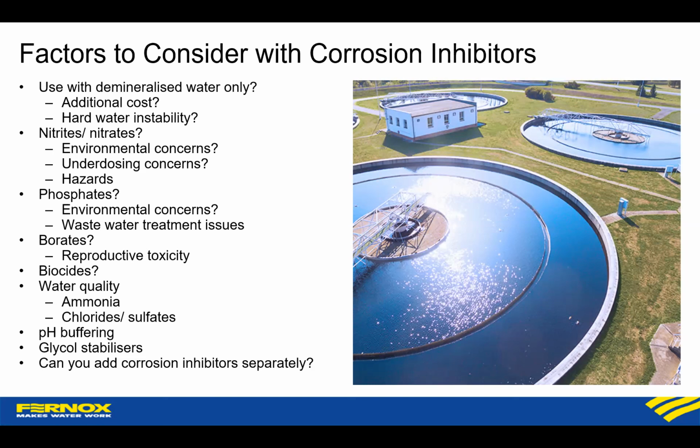Borates are largely something of the past. I know Fernox changed over from about 2010. There started becoming hazards associated with them, but you do still see them on the market. But that should be fairly obvious by the hazard labelling. You'll see a sort of exploding body, we call it. It's like a silhouette of a person with the organs highlighted, because it's a reproductive toxin.